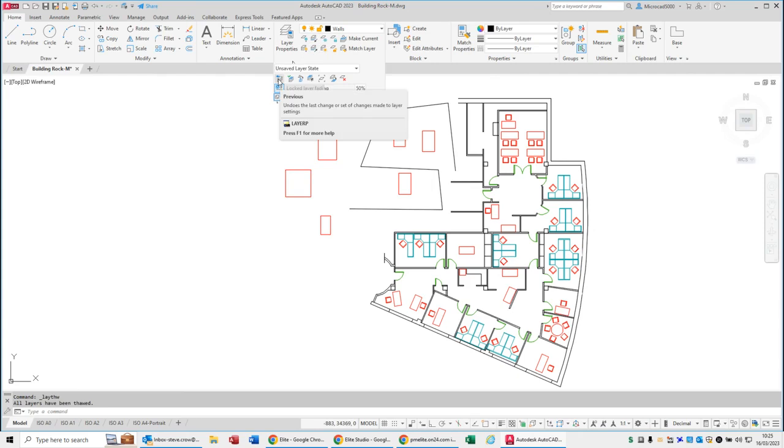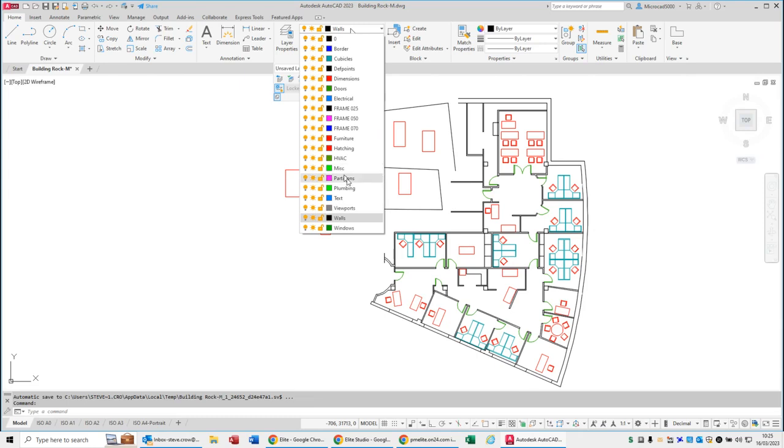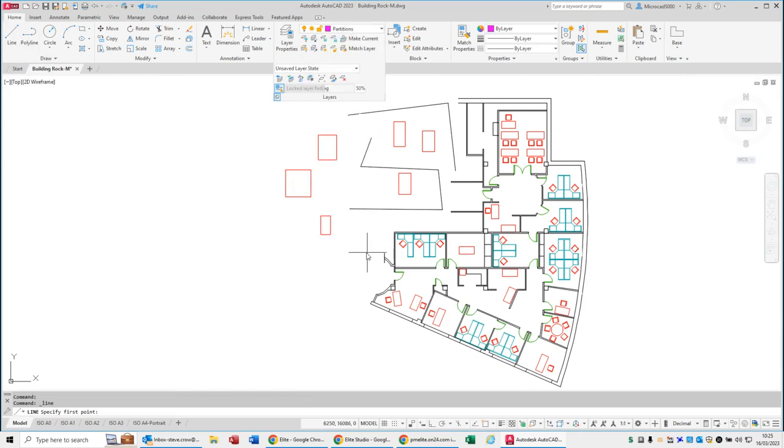So what's this then? It changes to the current layer. If I draw some objects on the wrong layer, it's a bit of a weird one. I can't see myself using it very often. If I switch to the walls layer, and then say change objects to the current layer, pick the objects, press the enter key, and it moves into the current layer, which happens to be walls. Bit of an odd one. I can't really see that one being used very much, but there you go.